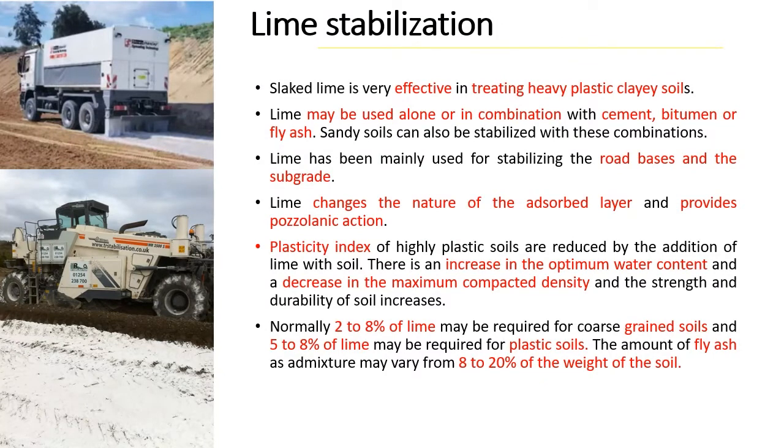The third admixture used for soil stabilization is lime stabilization. Slaked lime, calcium hydroxide, is very effective in treating heavy plastic clayey soils. Lime may be used alone or in combination with cement, bitumen, or fly ash. Sandy soil can also be stabilized with these combinations.